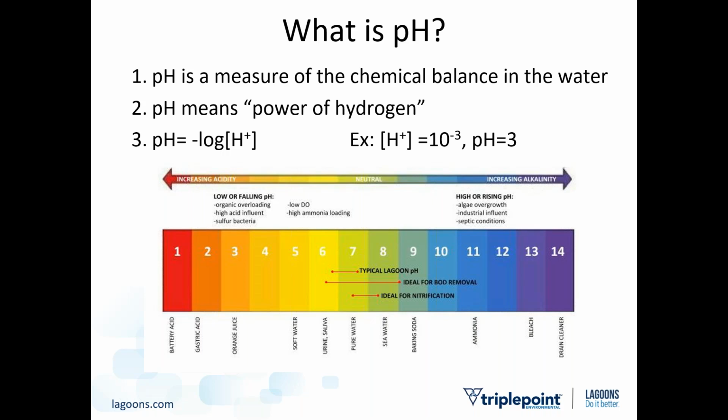One particularly tricky, picky type of bacteria that we'll talk about more later are the bacteria that do nitrification, ammonia removal. They are very specific in what they want. They want a pH ideally in the upper 7s to low 8 range to do their best work. And if you get a pH much below 6.8, they actually start to die.